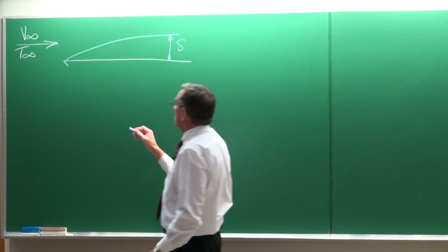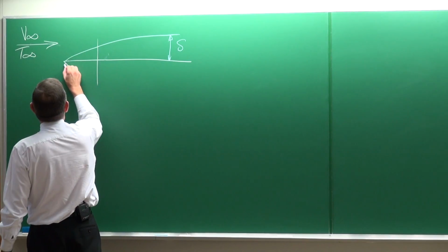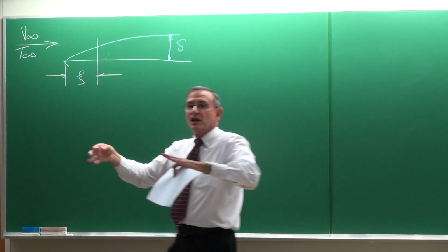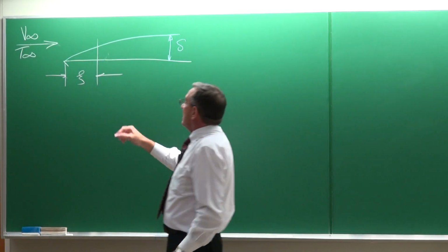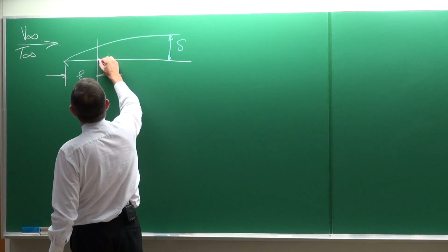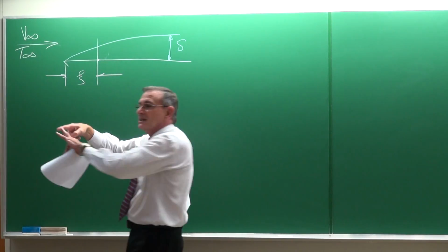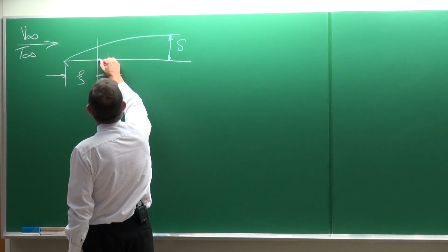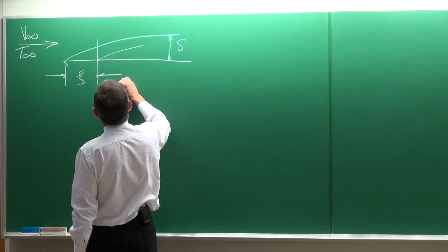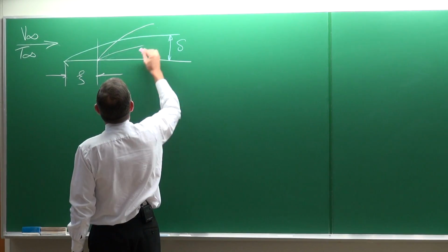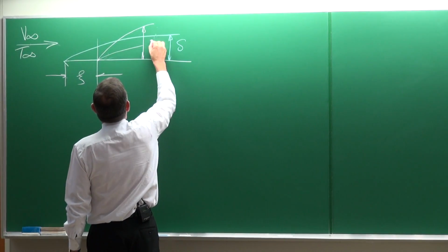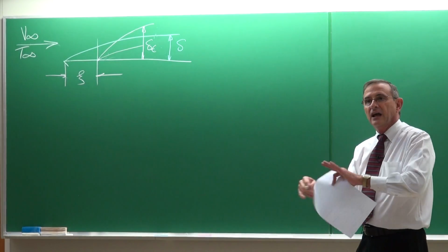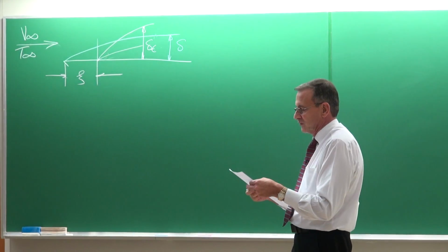And then there's a special case where we've got this distance psi, in which there's no heating or cooling. And therefore, the heating and cooling will only start at that point there. So it's an unheated length in the first part. Depending on the Prandtl number, the thermal boundary layer can develop like that, or it can develop like that. So there are also some solutions in your textbook for this specific case. Again, from first principles, you can actually solve that.